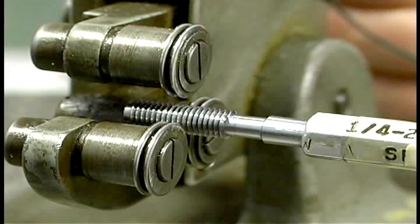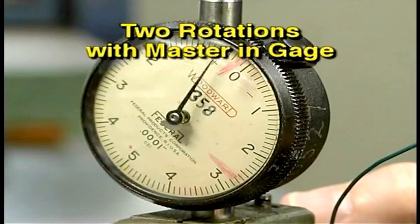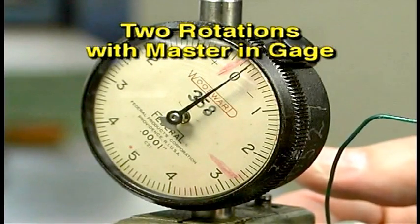Press down on the opening lever and place the master between the rolls again. As you release the lever, note the number of times the needle rotates. In this example, 2 rotations.